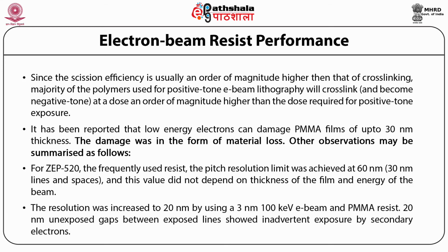Secondly, if the resolution was increased to 20 nanometer by using a 3 nanometer, 100 kilo electron volt E-beam and PMMA resist, 20 nanometer unexposed gaps between exposed lines showed inadvertent exposure by secondary electrons.